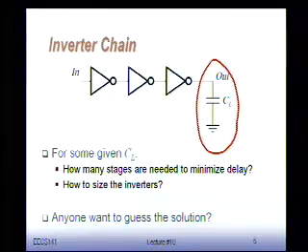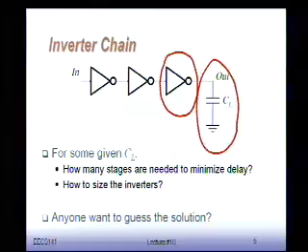So somewhere I have a large capacitance to drive, and I would like to do this fast. The challenge is how to do that in the best possible way. As we discussed last lecture, the best way to drive a capacitor fast is obviously to use big transistors. Make them as big as possible. But then you have the problem that if I made this inverter really, really big, and drove it directly from a very tiny inverter in an ALU or something like that, I've just moved the problem forward, because the input capacitance of those big transistors is going to be huge as well.